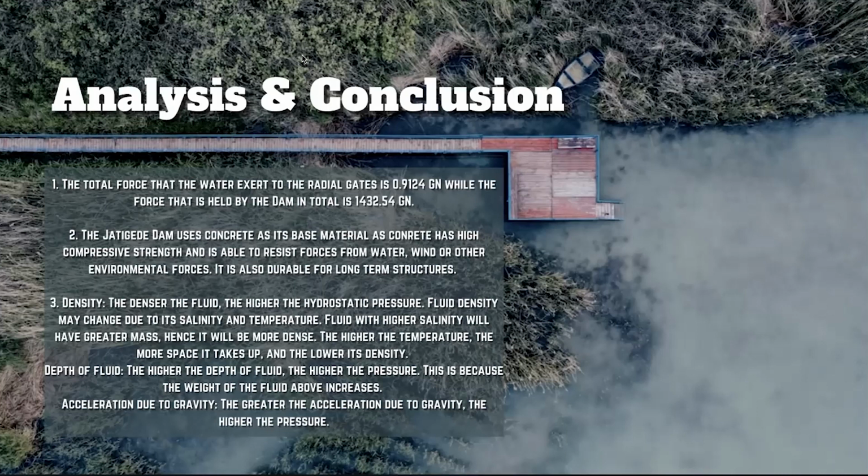The depth of the fluid also affects the hydrostatic pressure. The higher the depth of the fluid, the higher the pressure. This is because the weight of the fluid above increases, therefore increasing the pressure. As for acceleration due to gravity, the greater the acceleration due to gravity, the higher the pressure. Those are some of the factors that we have concluded might affect the hydrostatic pressure.